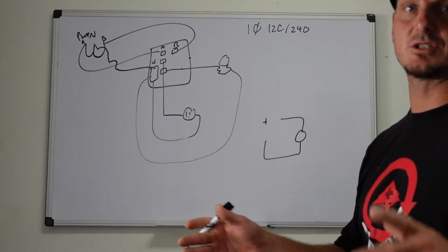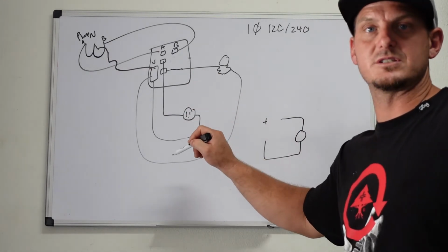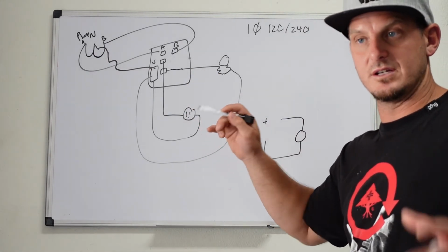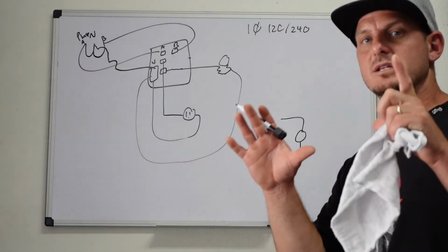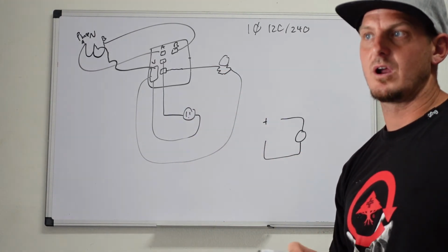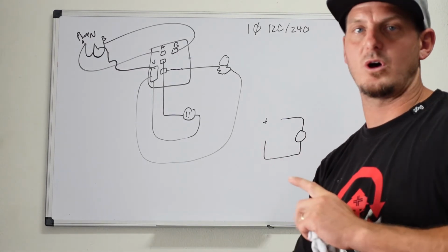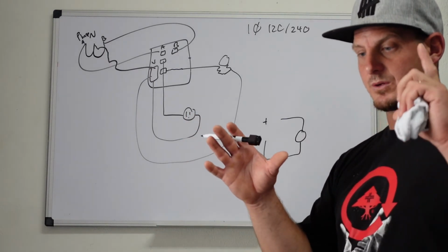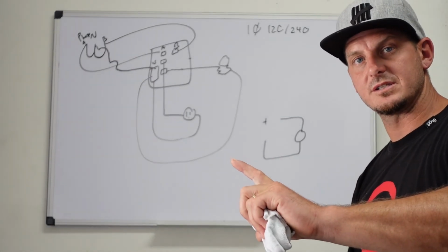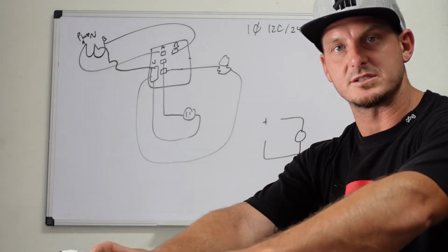Now that will change as loads change in your house. Generally, you will never see just a series circuit or a whole system with the transformer, the panel, and everything in series. Very rare, unless it's some type of dedicated equipment for that. Normally it's all going to be parallel as a system. Now you can have the circuit in series and another circuit in series, and it will make a parallel system.